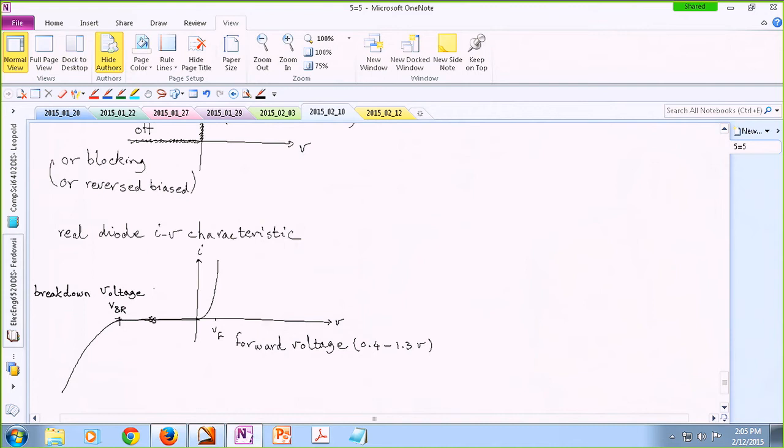So these are called the static characteristics. So if you want to model your diode, if you want to have a more accurate model of your diode, this VF is actually representing some losses in the system, right? So you can either just include VF, or you can also include a little bit of a slope over there, which is represented by a resistor.